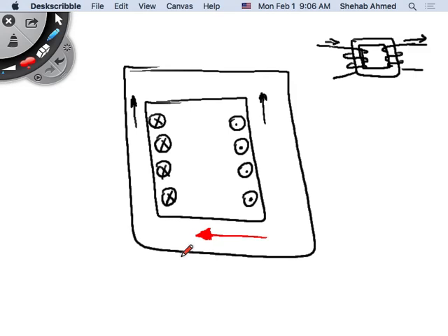Think of it. If there is a difference between them, it's because the reluctance in the core required some additional flux to build this magnetization system, right? Because again, the number of turns here multiplied by the current coming in, and the number of turns here multiplied by the current coming out.